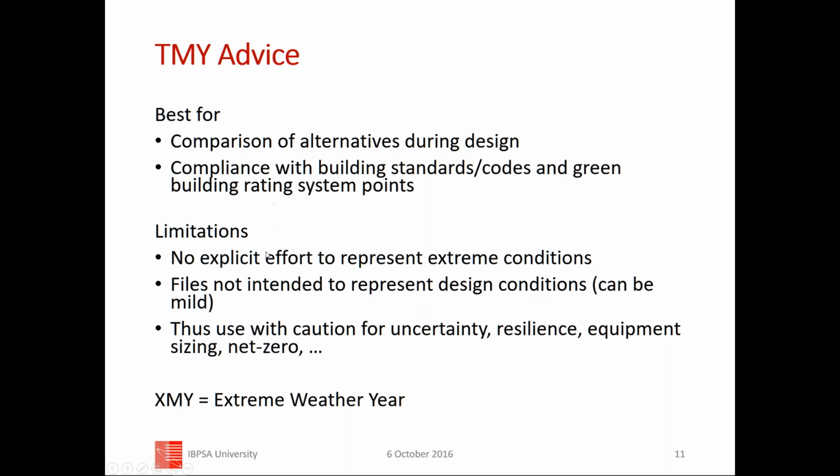But the problem with TMYs is that, except for the statistical cumulative distribution function, there's no real effort to represent extreme conditions. And so you can't really get design conditions. Sometimes the years are somewhat mild.